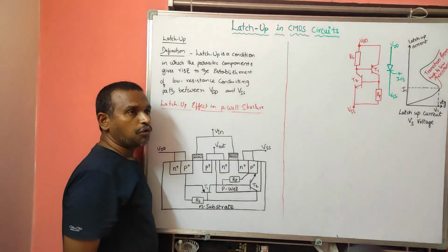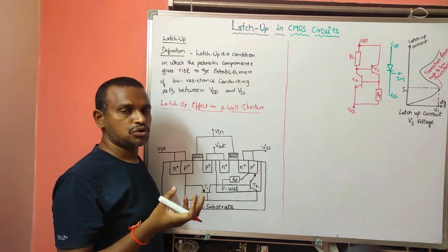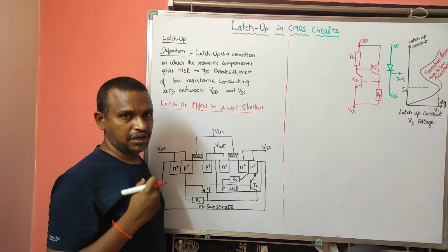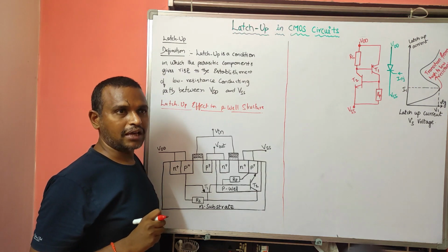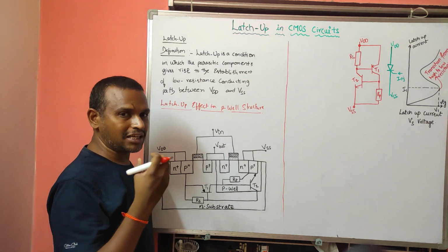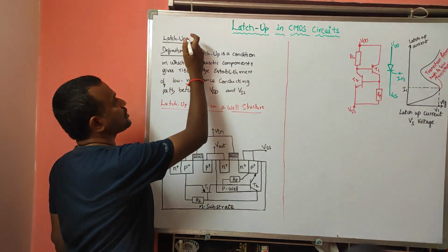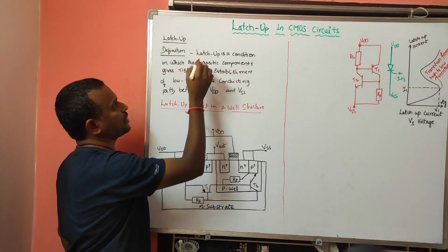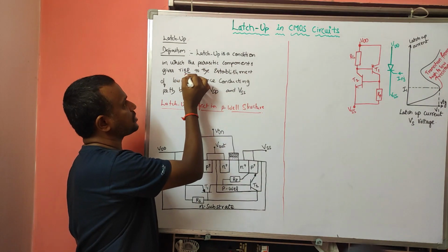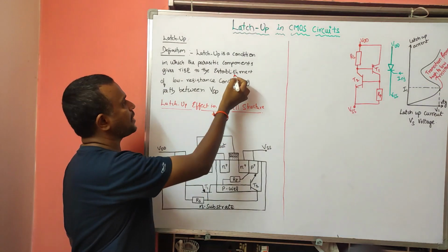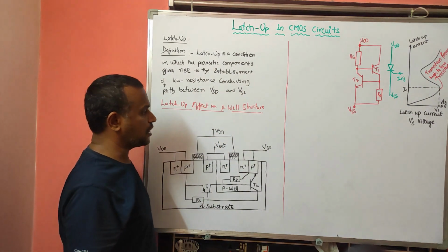Okay, so where do we get this? While doing the fabrication, we get this latch-up condition, due to the formation of parasitic elements. I will explain what the parasitics are here. First we will go with the definition. Latch-up is a condition in which the parasitic components give rise to the establishment of a low resistance conducting path between VDD and VSS.